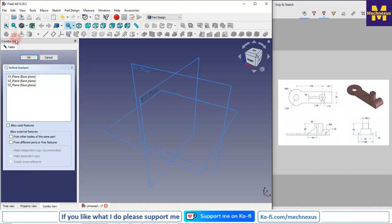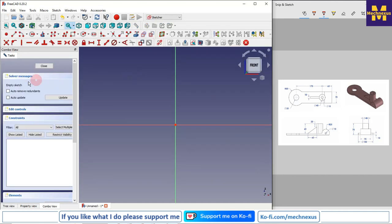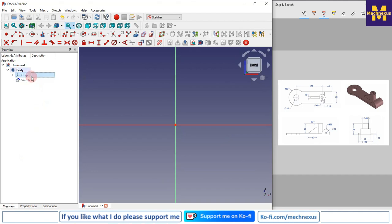Now I will create the sketch, and for the sketch I will select this XZ plane, and now I move to the tree view. As I am in the sketcher, first I will draw my sketch. For this I will keep my center here, or I can draw from this origin as well. I would keep it as simple as possible.